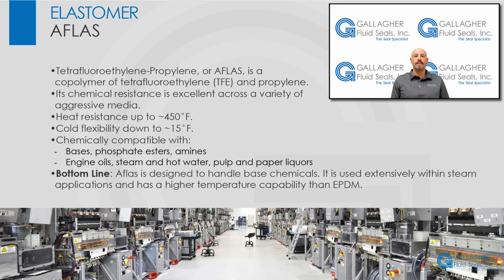The bottom line is that AFLAS is a fluorinated elastomer. However, unlike traditional FKMs that perform well in acid applications, AFLAS is designed to handle base chemicals. AFLAS is used extensively within steam applications and has a higher temperature capability than EPDM.